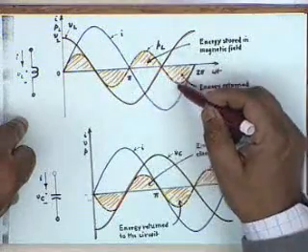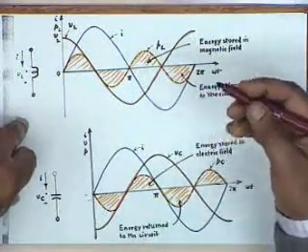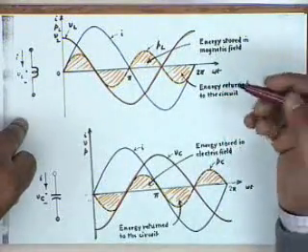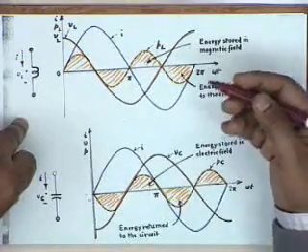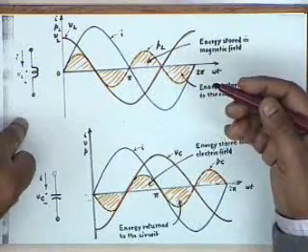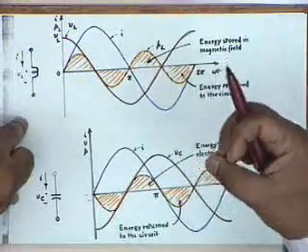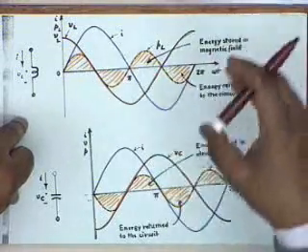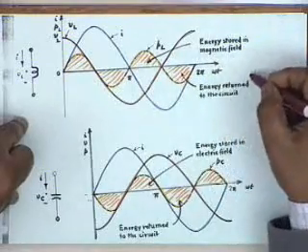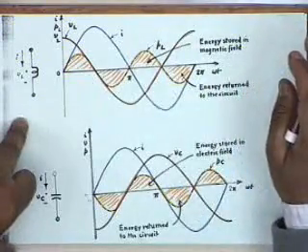Alright. So, in the next quarter of a cycle, the power is negative, which means that the magnetic field is returning energy to the circuit. That is, the inductance no longer stores magnetic field, stores energy, no longer takes energy into its magnetic field. This energy that was stored is being given out, so that at the end of this, again the energy becomes 0, and again it stores, again it returns, and this goes on. So the average power is equal to 0.